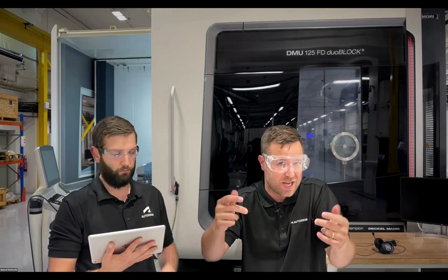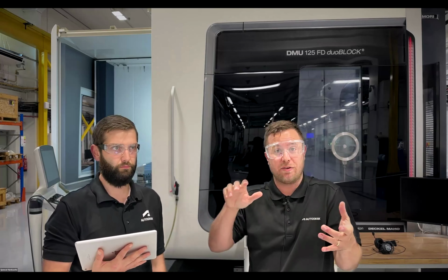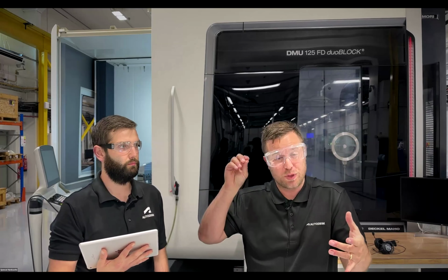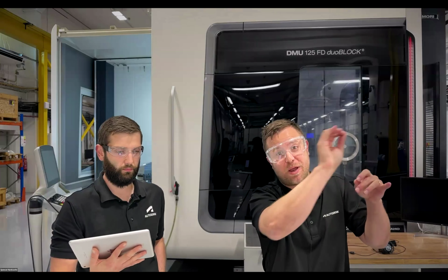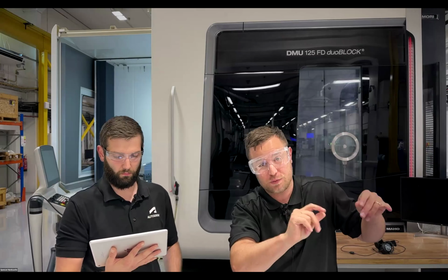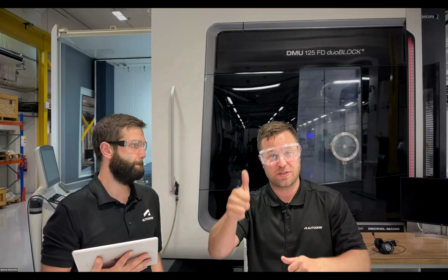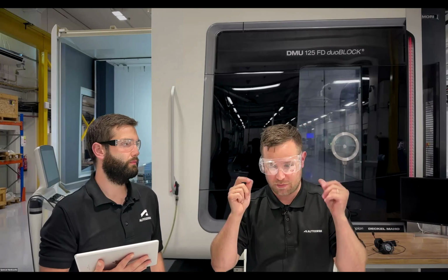So all you need to do, if you're using the container method, is simply drop your part in. And when you're in your setup with your stock, you identify the top level stock container, not the actual file that you've dropped in. Then whenever you drop a new file in, it automatically recalculates. That's a hint. But yes, there are fixtures all available, ready to use inside of Fusion for you today.